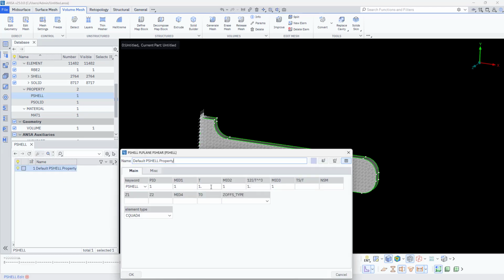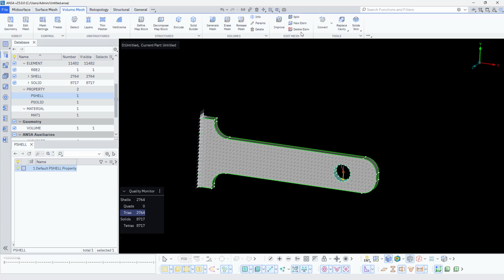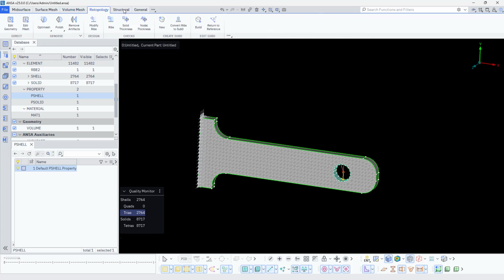Yeah. So thickness I'll assign here as 0.01 because the shell I'm not going to consider at all. It should be treated as a membrane only, just for reference. So we are running the solid volume analysis on this solid model in short. You can even delete the shell completely, no issues, but if you keep it as membrane, the impact is very minute, that is least.